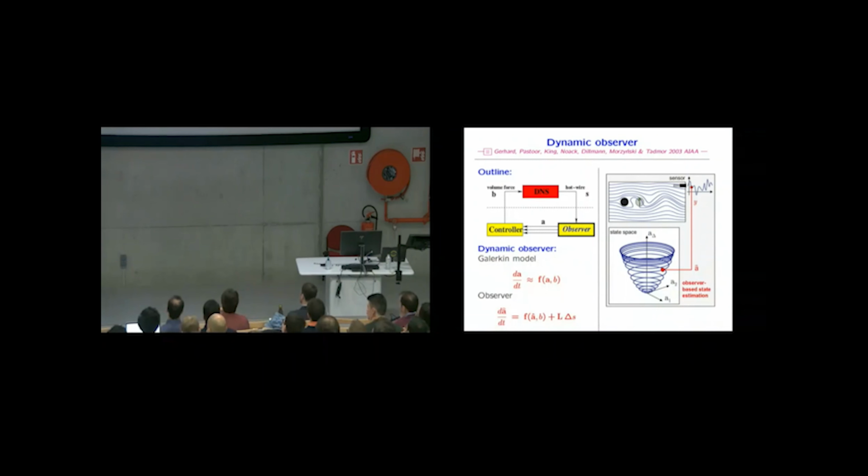So here we do it, sensor signal. So we have the history. So this goes now in the past. And essentially, using this history and the dynamic observer, we can pinpoint a location on our paraboloid. So with that, we can now estimate the full state from the sensor signal, and we know how to actuate for the full state. So we have a control design.